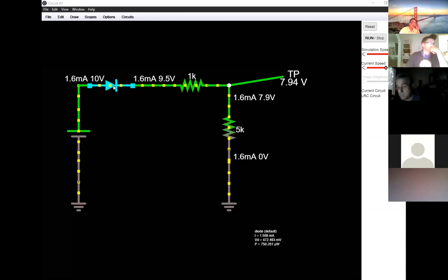If you slowly work with it, you can figure out just some basics. Just remember, you can highlight each component like the diode, and then the lower right shows you the value at the time that your voltage and current is flowing through the component.